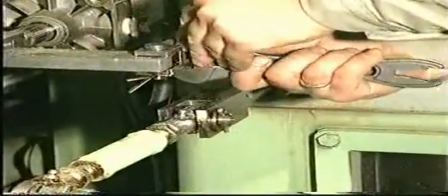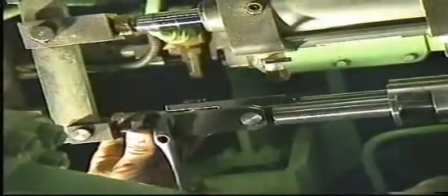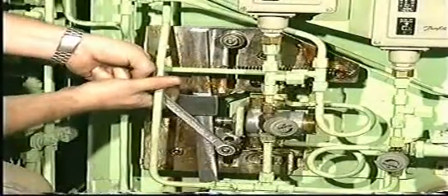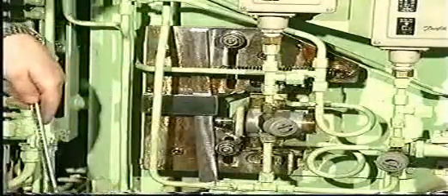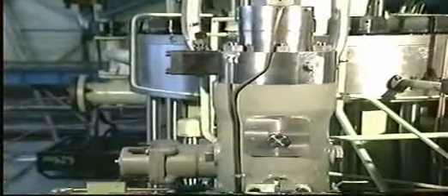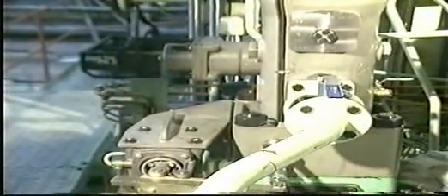Fine adjust the links so that the maximum combustion pressures, corrected to ISO ambient conditions, are uniform and have the required value. Load the engine until it corresponds to 100% MCR and fine adjust the lowermost pivoting point so that the maximum combustion pressures, corrected to ISO ambient conditions, are uniform and have the required values. Cams must be turned if the value calculated in step 1.4 of this film is exceeded.